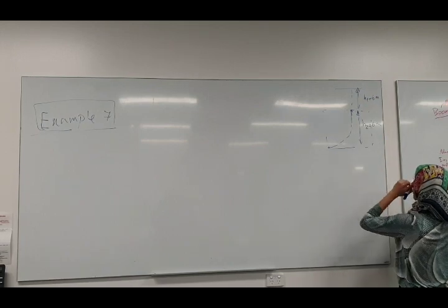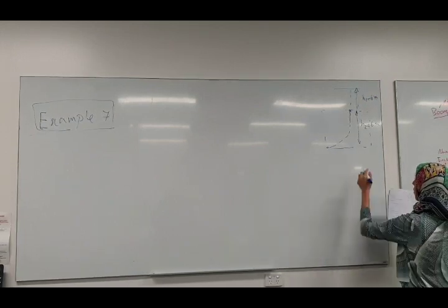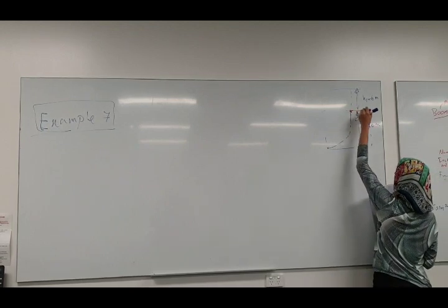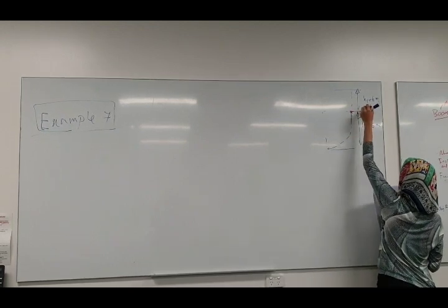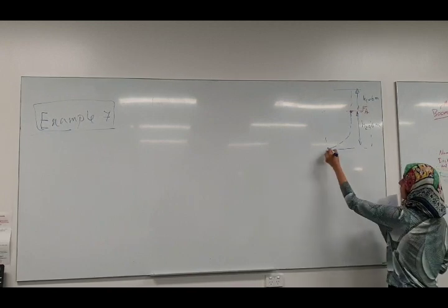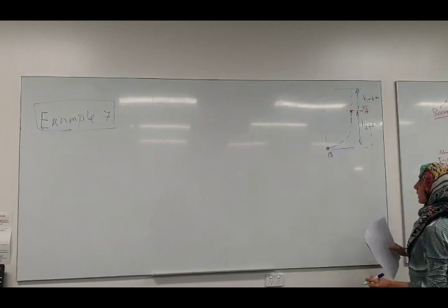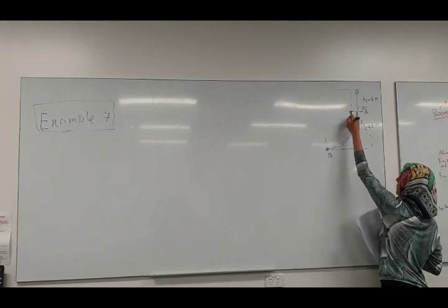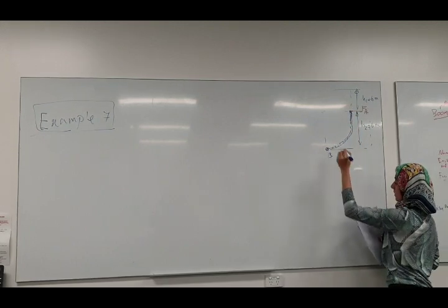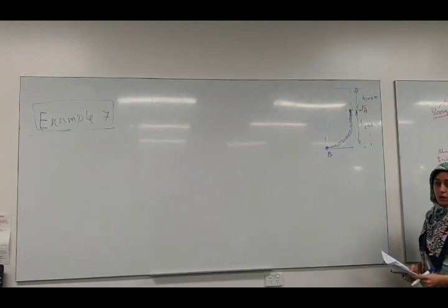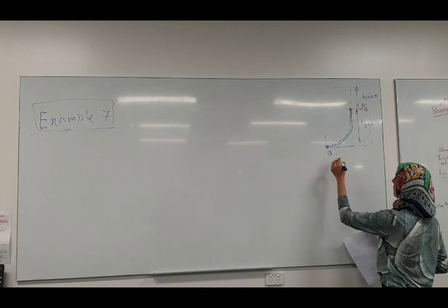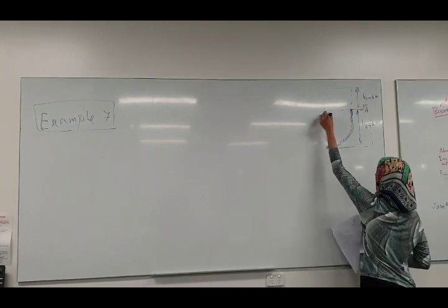And this H is about 6 meters as well. So we want to find the force required at point A to keep the gate closed. That's our gate. As I just explained, how we're going to solve this one, we have a 3-component contribution, right?